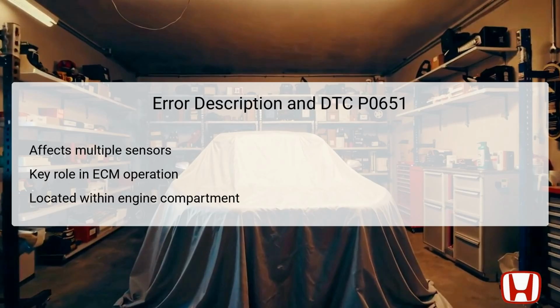Lastly, the FTP sensor measures the fuel tank's pressure to assist in the vehicle's emission control system. All these sensors are typically located in the engine compartment, where they interface directly with the ECM and other systems. Issues in any of these areas may trigger the DTC P0651 error, leading to reduced vehicle performance and efficiency.